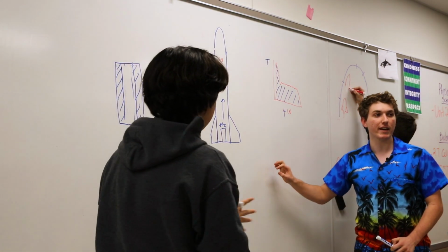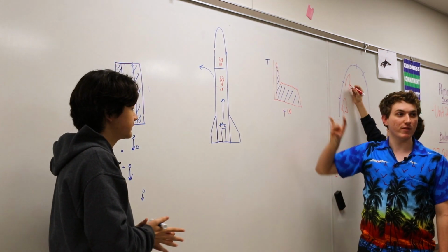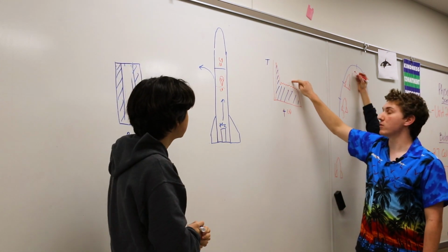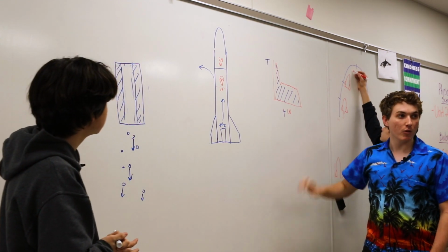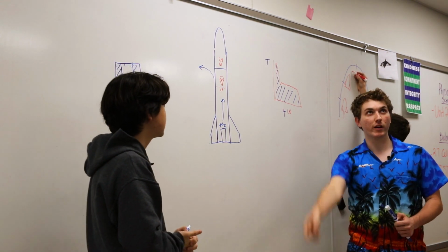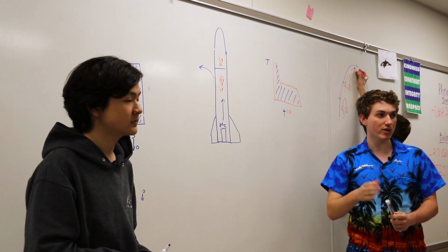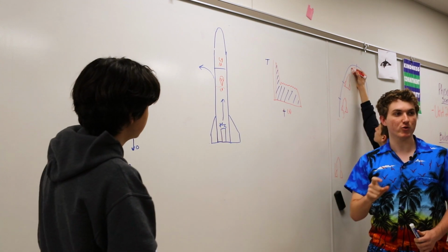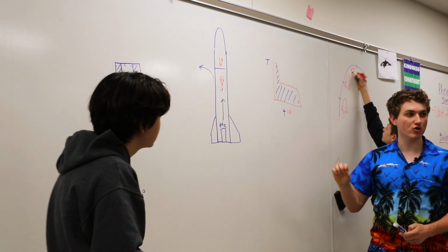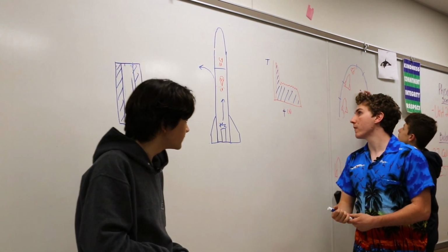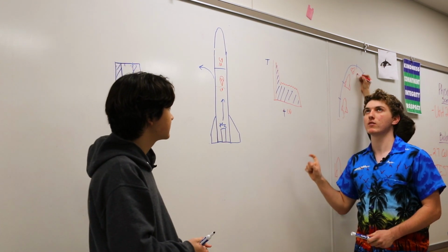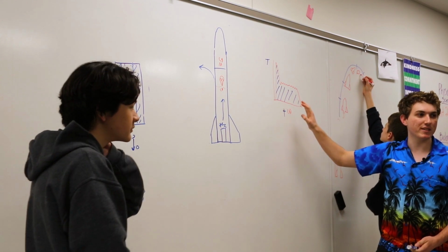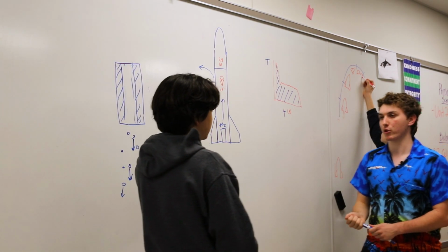What's important to understand is that at different points in time, there are varying amounts of thrust. Right at the start, there's a big burst, and then there's a long sustain, and then it stops burning. The rocket goes upwards for, I want to say, 10 seconds or so, but only 1 second is it actually burning. The important part is it burns for a very short period. The amount of force changes throughout, and you can classify it. Most of the time when you're looking at motors, you look at the thrust curve, but at a basic level, you usually just look at the motor code.